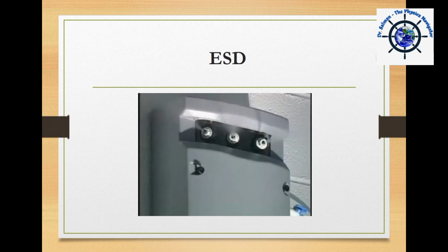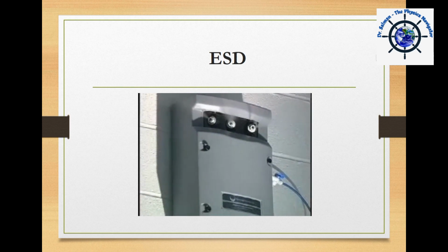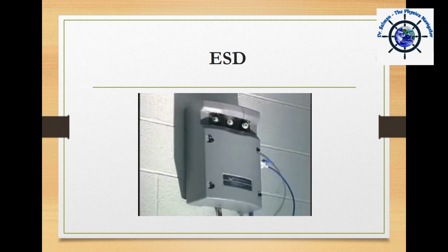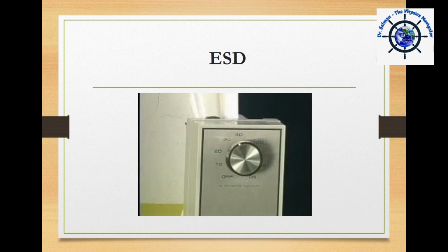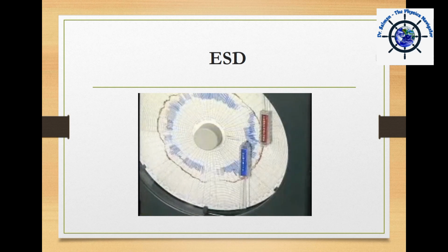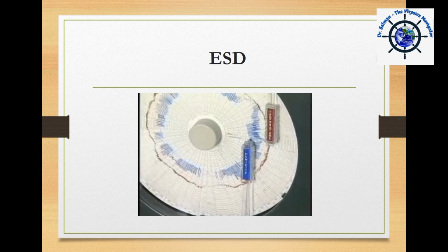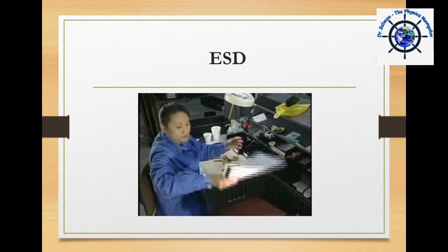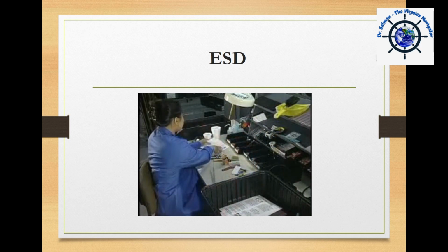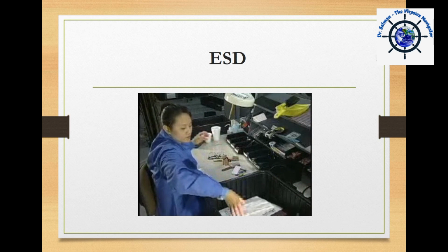In addition, humidity control can be used to help limit charge buildup. Not only do ESD problems become much worse when the relative humidity drops to 30% or less, but some low-charging and dissipative materials become ineffective at low relative humidity. Again, the best ESD control solution is to eliminate the materials that generate and hold static charges.